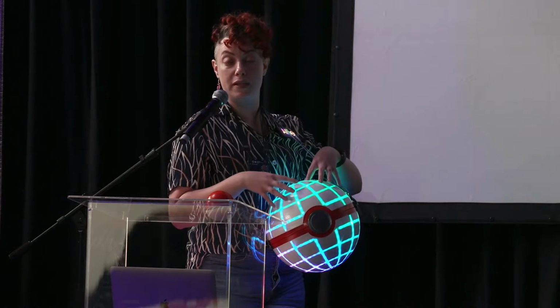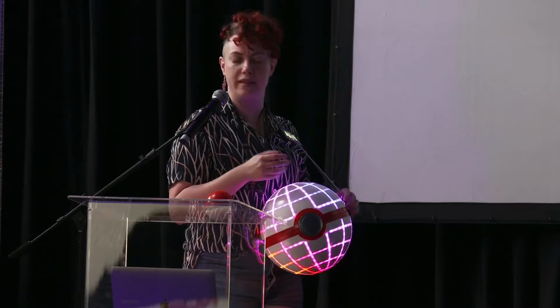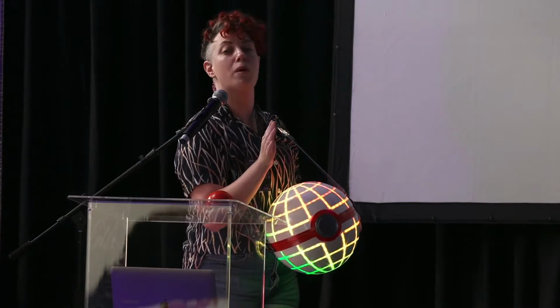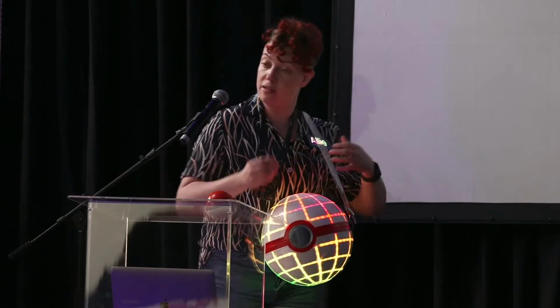My only warning would be to take it slow, because in my first couple of attempts, I got real slap happy with it and just poured IPA all over it. And again, it melts with IPA, it really did not go nice. Now, mind you, this is also going to be a problem specifically with these prints because they are thin. They aren't thick layered prints. If you have a print that's, say, 2 millimeters thick and you can do more walls in it, you're probably less likely to have an issue. For this, it was challenging. But yeah, take it slow and be patient. The results are worth it, I think. Any other questions?